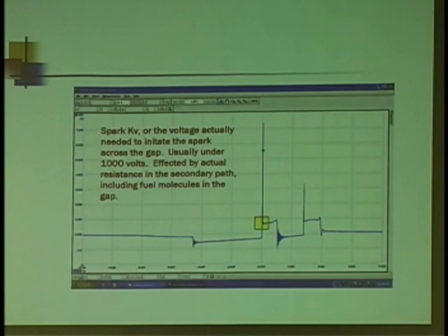The next point of interest is the spark kV. Spark kV is a measure of resistance. If I've got a high resistance wire, it's not going to show up in firing kV. Don't believe me, put about 8 feet of ignition wire on in place of a 2-foot section and check the scope pattern. It's not going to change much. Maybe the spark kV will change, but not the firing.